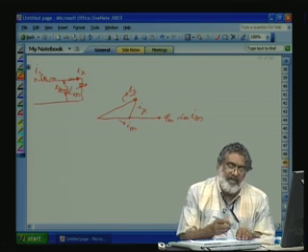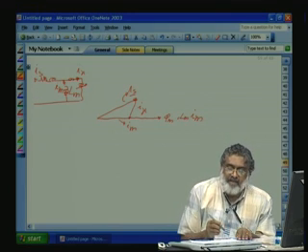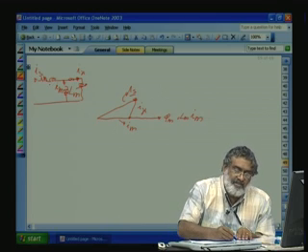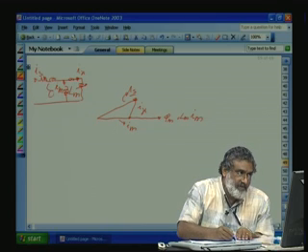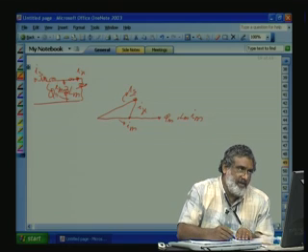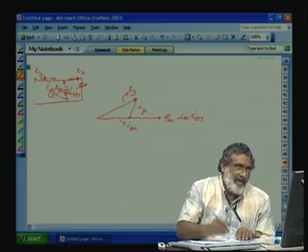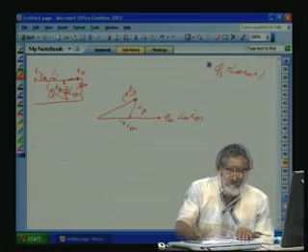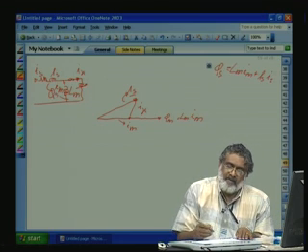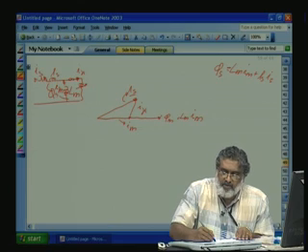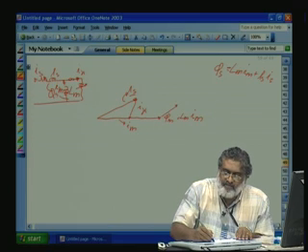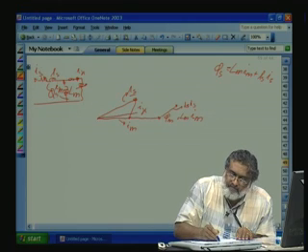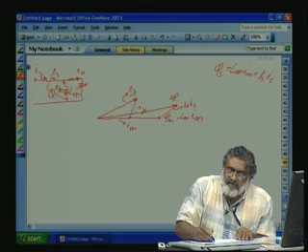Now, from this equivalent circuit, the stator flux is coupled by these two inductances. Phi s is equal to LM IM plus LS into IS. So IS is proportional to this one. Along this direction, this is LS IS, and our phi s is here.